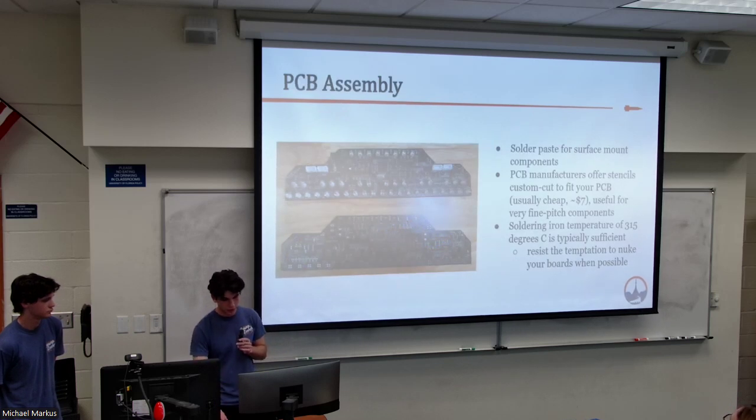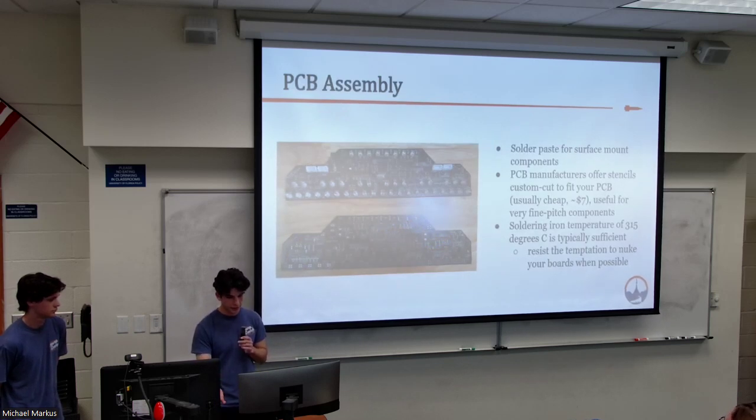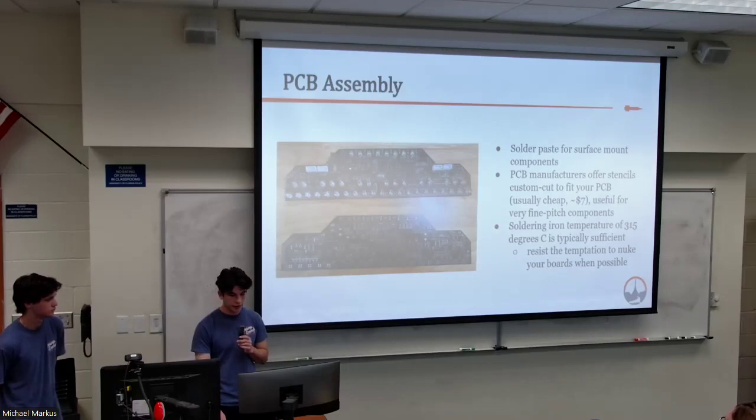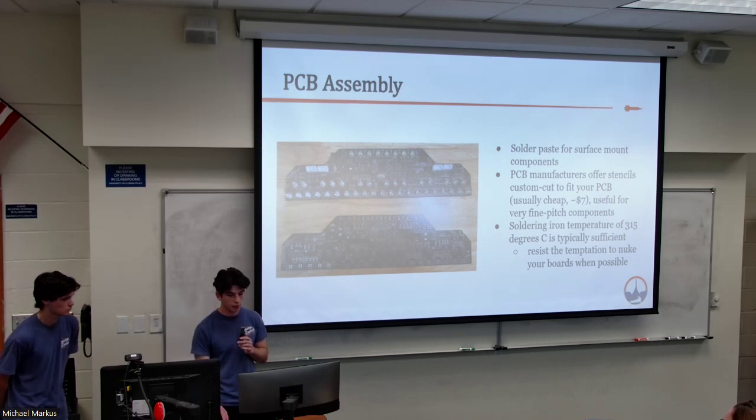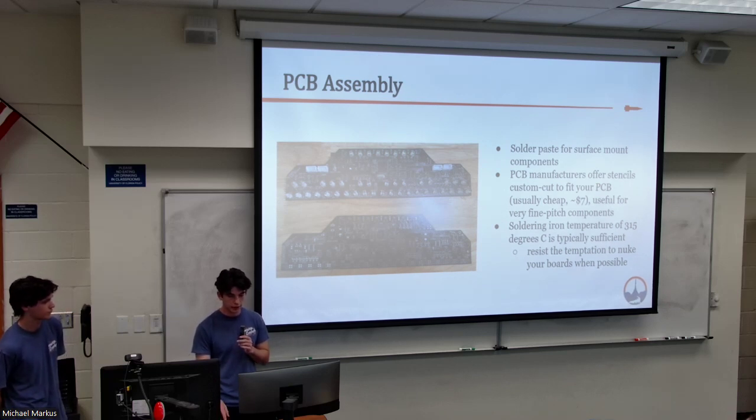Yep, this is pretty much what I was saying earlier, where you can buy stencils. You want to use solder paste when possible. It makes it much easier. And for soldering, you don't want your temperature too high, or else you will burn the board and components, which usually, at least for the board, is not a problem. But sometimes components have something called a solder reflow curve, where it will actually damage the internals of the components if your temperature is too hot.